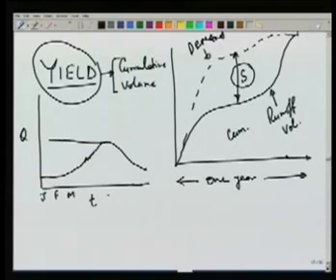Hydrograph will give us what is the maximum flood in the river, so we can use that to design flood control works. We also have this minimum flow here, and as we have discussed earlier, there are three different kinds of streams. We have perennial, and if you draw this hydrograph for perennial, you will see that throughout the year there will be some water available in the stream.